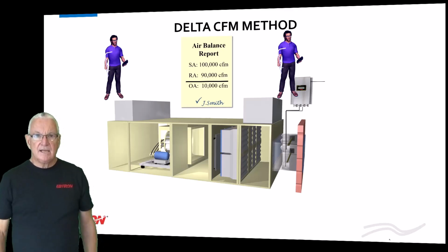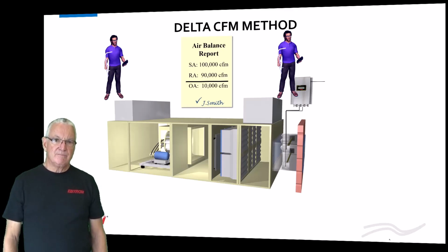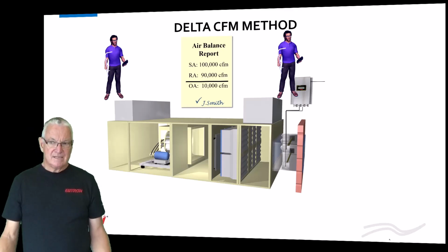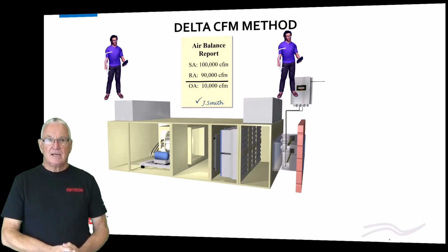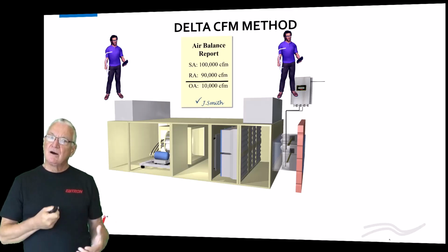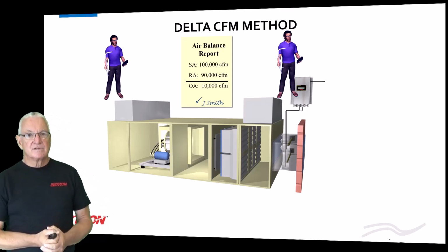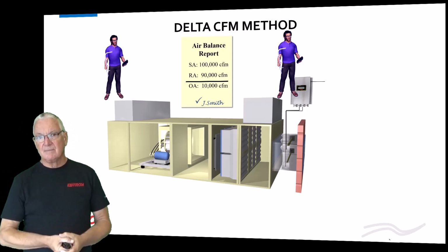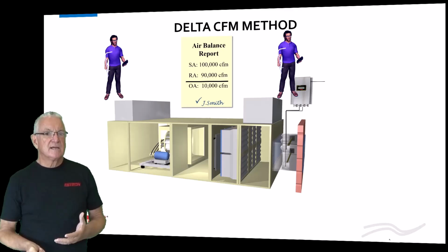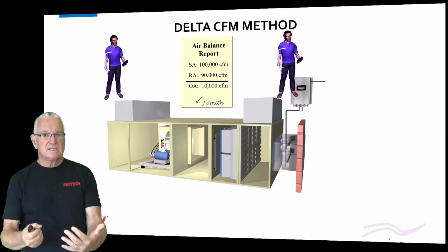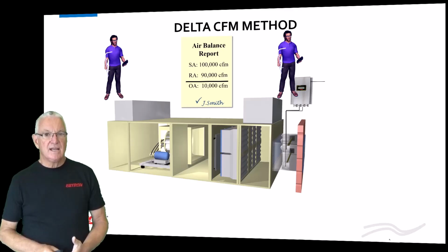So it's going to be like, okay, how accurate do you think you can do this measurement? And it depends on who you talk to. I mean, some people feel like they can get measurements within 3%. I know if you use EBTRON properly in the supply and the return in ducted systems, within 3% is very reasonable. Okay, there's other folks that'll say, I'll get within 5 or I'll get within 10%. Piezo rings, if they're getting within 10%, they're having a good day. So I'm going to use 3% just because it's on the lower end. It's probably as good as you're going to get, okay?